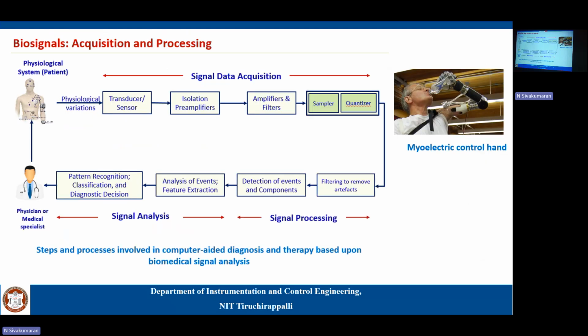Whenever we record data, because now we have wearables, we have seen the Ag/AgCl electrode a couple of days ago. Now the technologies are developing such that we need not use this gel electrode. We are slowly moving towards textile electrodes, which means on the cloth we wear, we can just embroider some electrodes, and with that we can get the data.